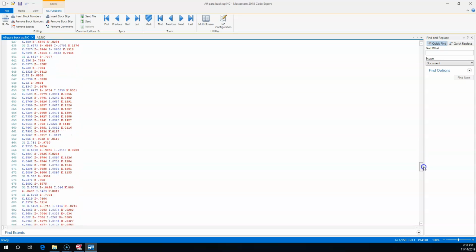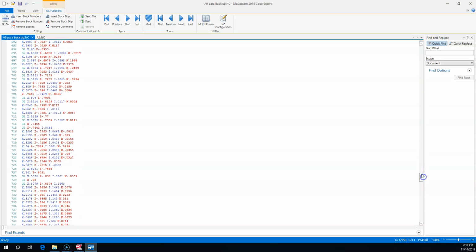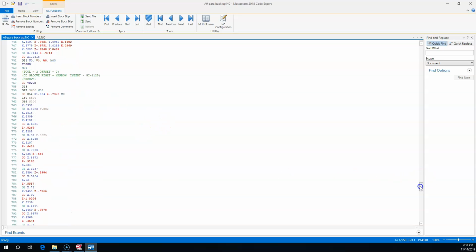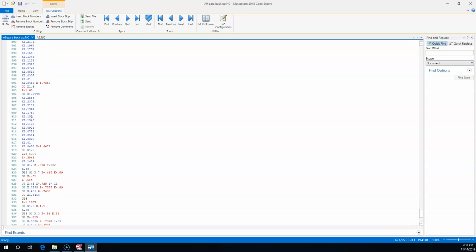And we'll look for that groove. Basically the groove's going to come in and start removing all of the material. So there we go. The OD groove brings in, has all of those X moves, moves over a little bit in Z, repeats the X moves, and as we bring it in, it's removing that material and giving us our clearance to make the geometry.